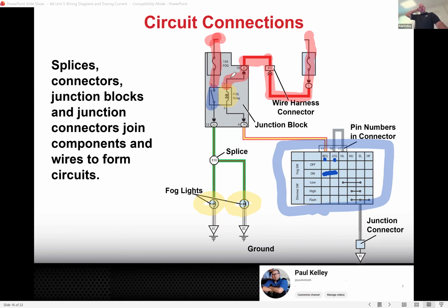And then it should really stop at that relay coil, which means technically I would be expecting ground on the bottom side. So let's see if the ground will trace out. It goes to BFG. Oh, wait, but we have the fog light switch on, so guess what it does? It's connected. So it then goes down to HL. Interesting. And HL actually won't make any connection unless we have the dimmer switch in a certain position.